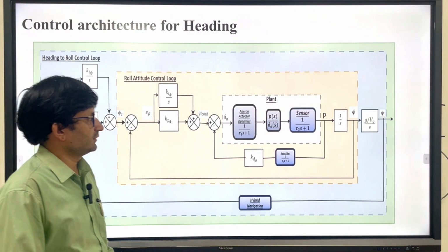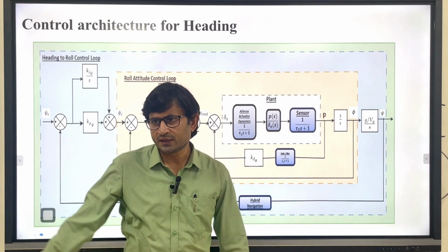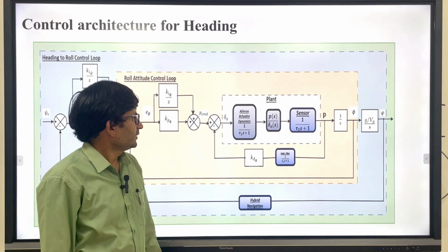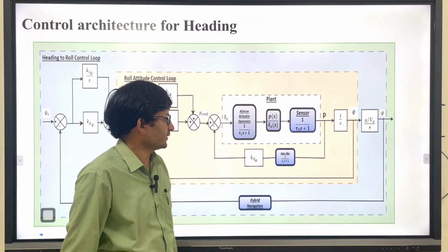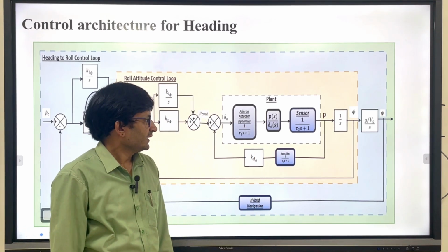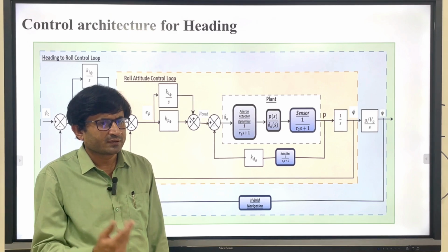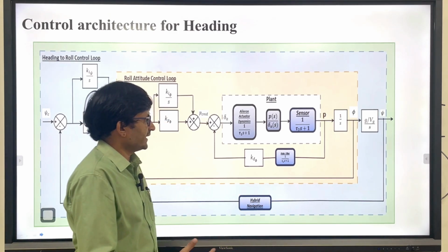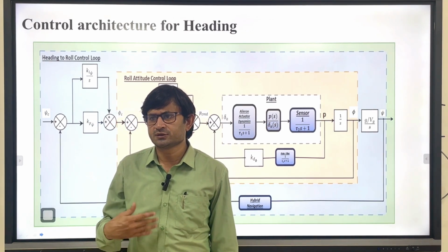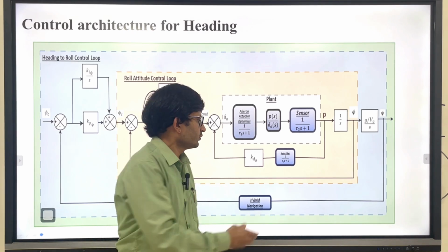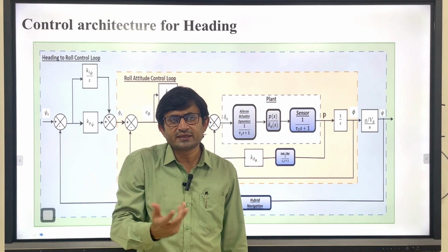And this is how you can understand it using a block diagram. First, in the last class we modeled the transfer function P by delta A, right? What you will do is take the actuator dynamics, put the position limit first and then the rate limit. Introduce a filter, and tune the gain to get the desired damping. When you do the open loop analysis you have a damping of 0.2, 0.3, but this is not sufficient. You have to go to, let's say, 0.7, so you plot the root locus and select the gain in order to get the desired damping.